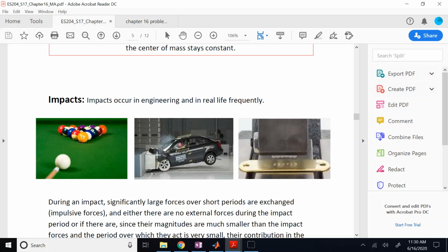What we call in solid mechanics, instead of elastic, plastic deformations. So deformations are plastic, they are permanent. Once the impact is over, the object is not going to get back its shape, it's deformed forever. And a lot of that kinetic energy is used to deform this shape. So this car is not going to bounce back with the same velocity that it hit this panel. If it bounces back ever, it's going to be with a very small velocity. That kind of impact we call plastic impact.